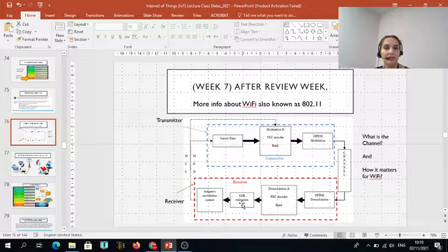And then we have this part here, which is very interesting. It is called adaptive modulation control. That means that I am continuously checking my system, how it is performing. And you can see that I have a feedback here. So I'm checking, am I doing good? Am I getting the signal that I'm supposed to get? Am I reversing the process exactly the way that it should be? And a part of that is the synchronization that I explained. So time and frequency should all be matched between the transmitter and receiver.